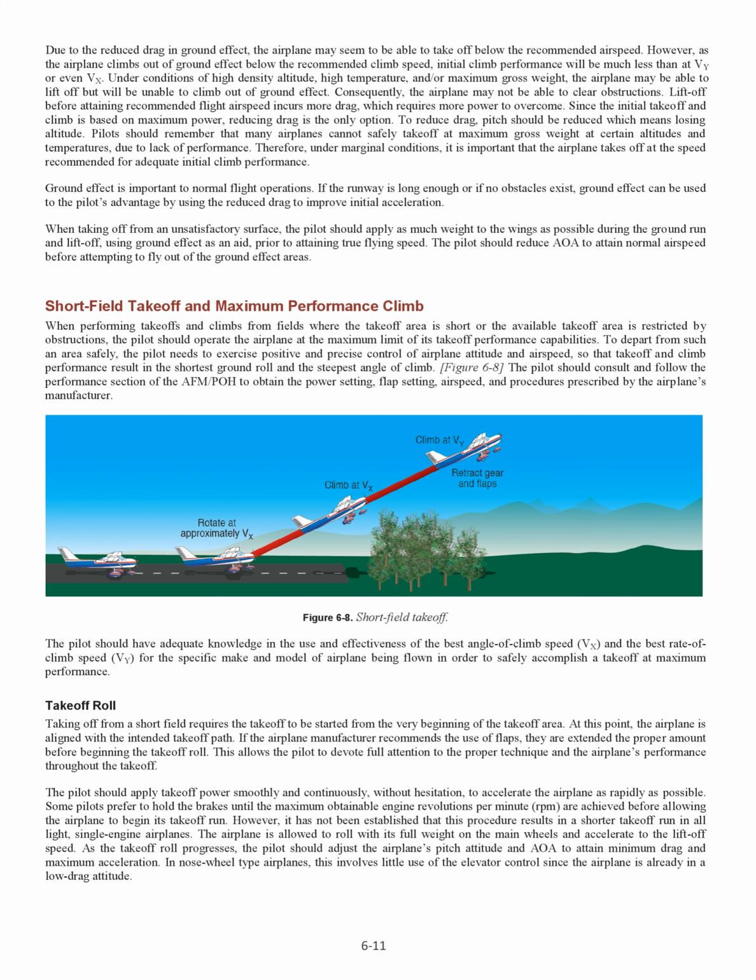Pilots should remember that many airplanes cannot safely take off at maximum gross weight at certain altitudes and temperatures, due to lack of performance. Therefore, under marginal conditions, it is important that the airplane takes off at the speed recommended for adequate initial climb performance.